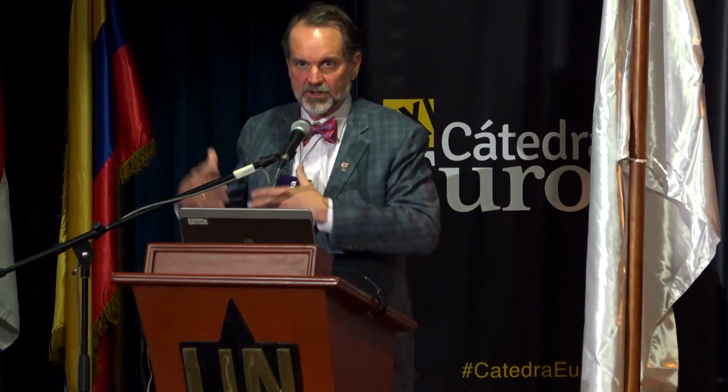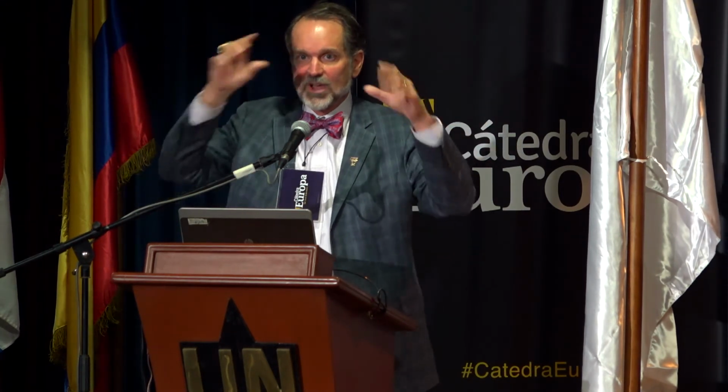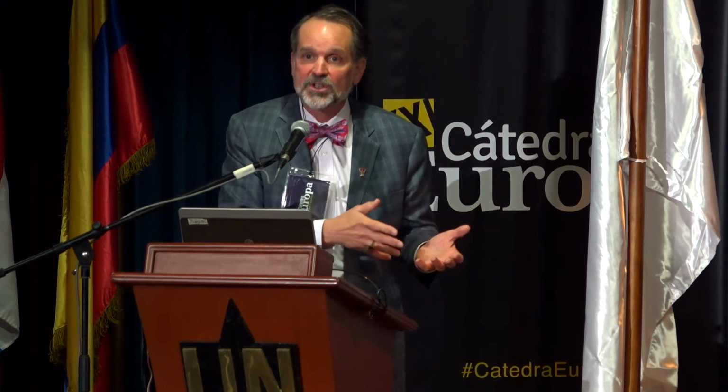The funny part is that you think, well, what is the concern with it? Actually it's no concern mixing with the guar and the gels, but it does cause an issue in the reservoir. It mixes with the water in the reservoir and creates concentrations of certain minerals that deposit scale, like gypsum or calcite. I don't know if you have hard water in Colombia, we have it in Lubbock. All our pipes in our homes, it's very hard water there, we have scale forming all over our pipes. So obviously that's 2 miles, 4 kilometers down, and that's very difficult to deal with if it forms those scales. That's probably our major obstacle.